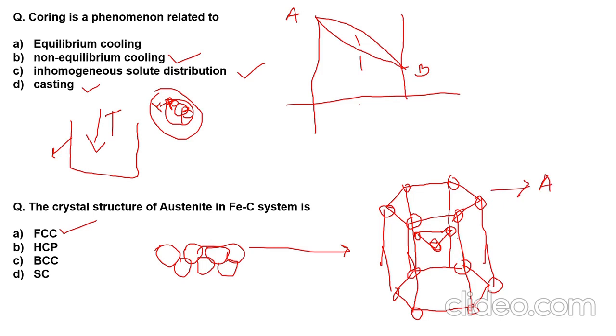And because we have a different arrangement of atoms stacked at the center, we have B, and then we have this which was similar to A, right? Because this is one unit cell, and there will be many more unit cells after this and before this. So the overall stacking of your hexagon will always be AB, AB type. AB, AB, AB will be the arrangement of atoms in your hexagonal unit cell. This will give you an idea of how atoms are arranged. If they are arranged in a similar fashion, you can name them by the same label, and once the arrangement changes, you change the label.